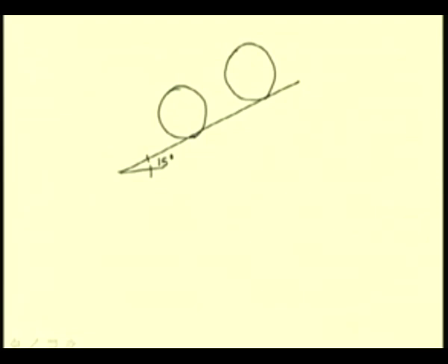At this point of contact for the roller, let us say the normal reaction is N1, and we have a frictional force F1 along this incline. Because this cylinder, if allowed, will try to slip in this direction, the frictional force has to prevent this slippage. So, at this point of contact, the frictional force is upward along the incline.